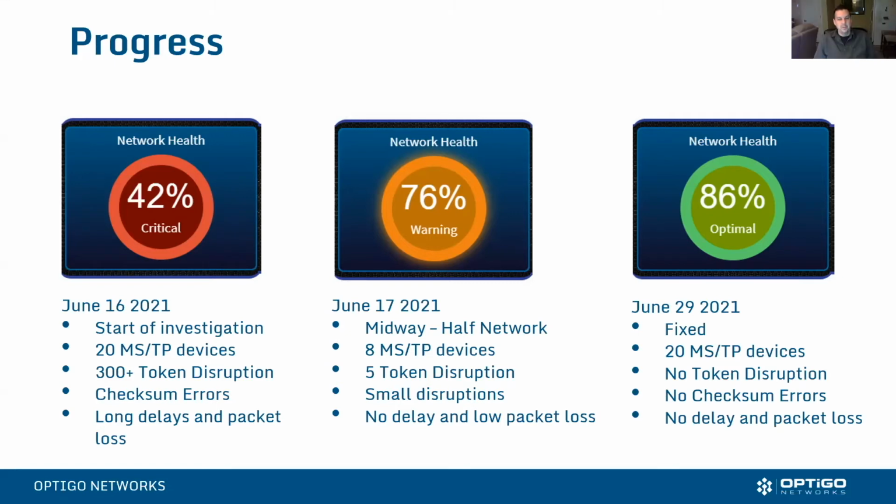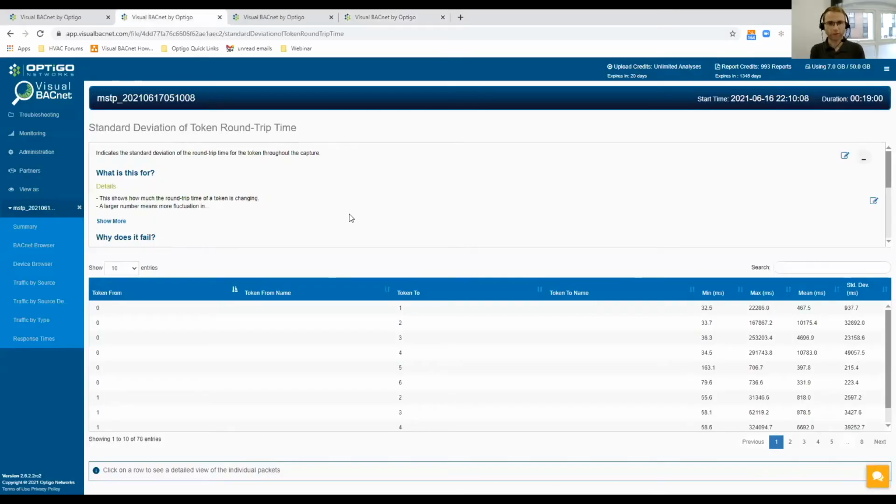Right, and in some ways it goes a little bit undiagnosed if things are working, except it doesn't really represent itself in the software. Yeah. What was your Desigo software showing? You did mention the devices are online and offline. Is that peer interrogation of the device, weird graphic data? Yeah, I think from memory, you would go look at a graphic to see what's the run hours of this pump or what's the current pulling, and it would just be zeros. There'd just be no data there, and a load of alarms against it because it can't pull that data back, and the objects were in alarm. So in the head end software, it gives us hundreds of alarms, because every time one of these objects can't be read, it goes to alarm. So from a housekeeping point of view, it's good to get these problems resolved just to keep the number of alarms on the system down.